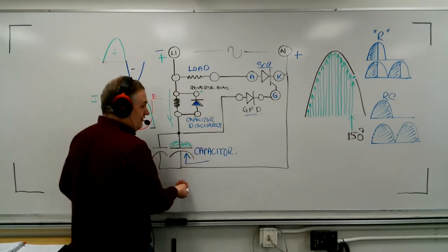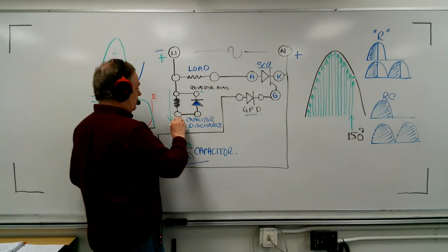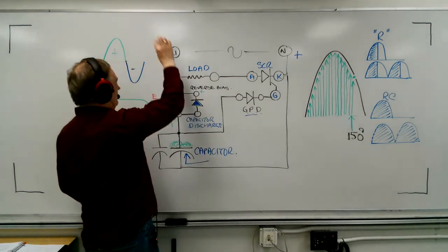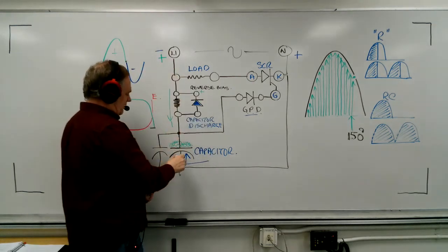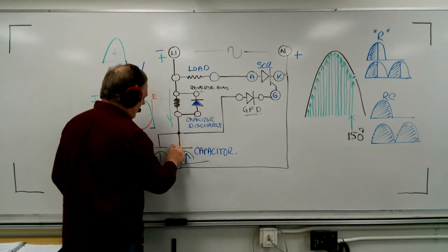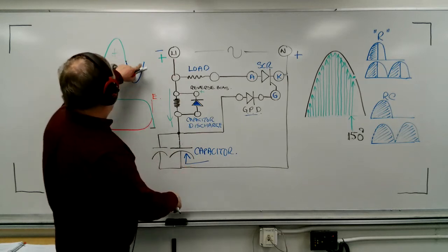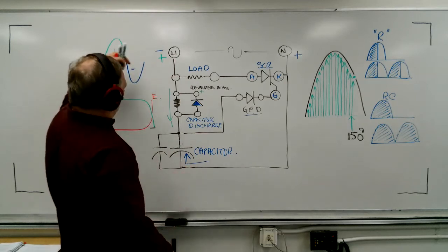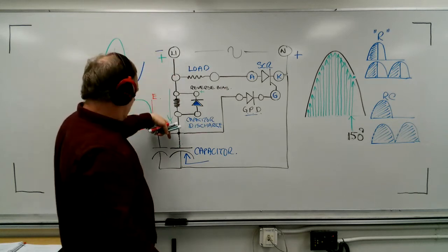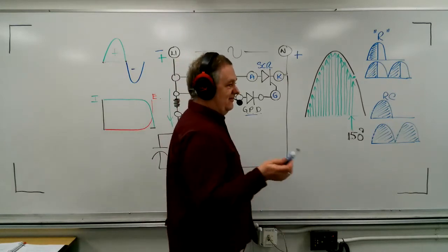So now what happens? The voltage is pushing here. This charge goes, oh, great. Blam, back to the line, and it empties this. And so now this is empty, okay? Your barrels are empty again. Now your voltage falls back to 0. And here we go, and we're gonna start flowing current in again, and we want to get our same firing angle. Now let me just ask you this question.